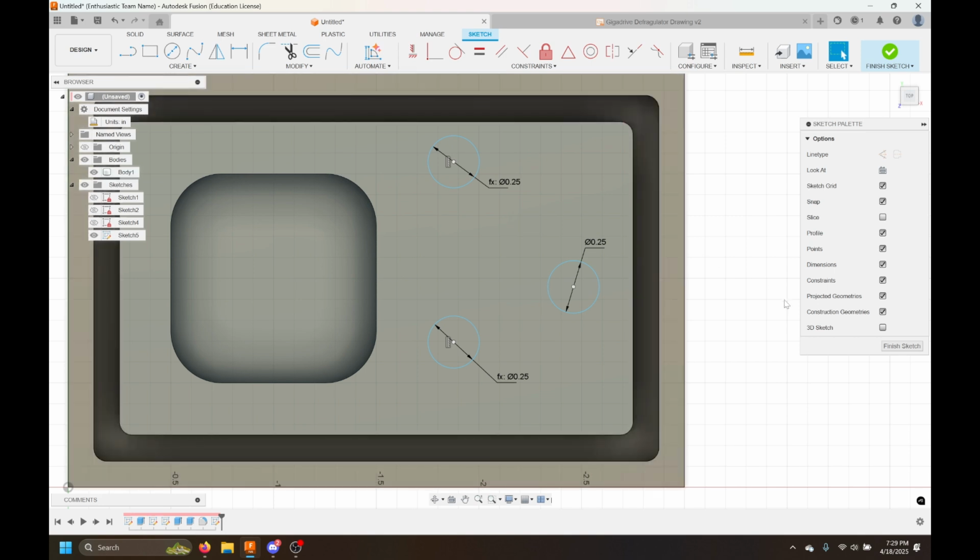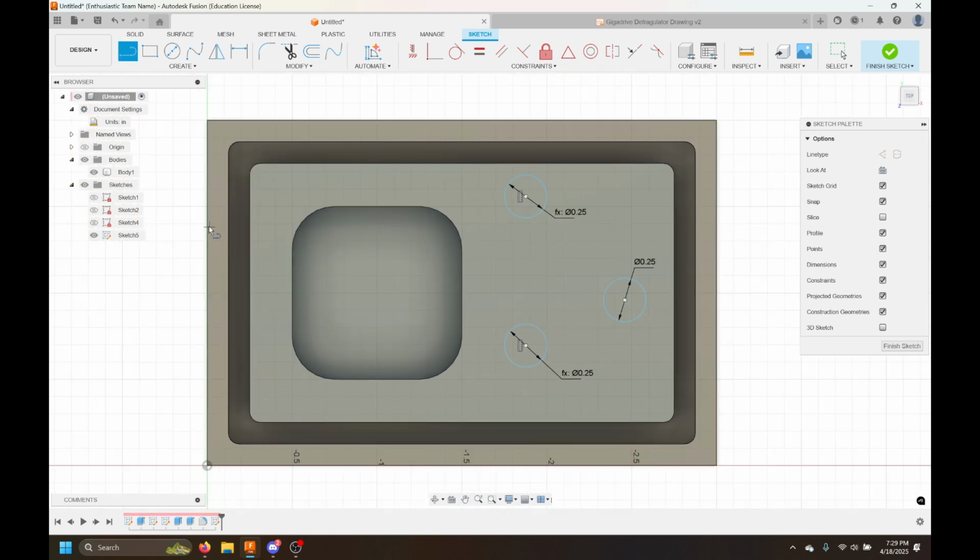From here, I'm gonna put down a line, so I grab the line tool. We made the sketch on this surface, so it doesn't see this outside surface. We're gonna go along this edge. And then right here, see that triangle is indicating it's the midpoint. So we're gonna put down a midpoint of our line and then a midpoint of our line over here.